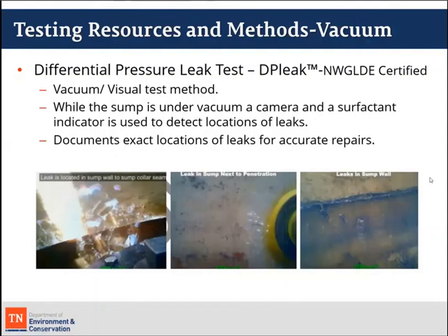David, is that kind of what you're saying, or did I miss it a little bit? Yeah, it's there. When we first saw that the state of Tennessee was requiring the Schrader valves to be removed to prove that there was hydraulic conductivity for your release detection, it's a great idea and it needs to be done.